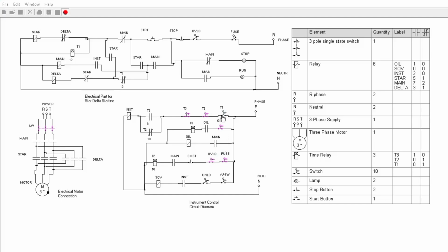For the last time we see again, we just okay this switch. This is not too much emergency, and this is for load and unload condition. After starting the motor or compressor, we can close this unload switch, that means load condition, and this air pressure switch. Automatically this air pressure switch will operate depending on the air pressure. When pressure is low, this will close, and when pressure is high, this will open. And this is the manual switch. Again we see this is closed, and everything is okay.